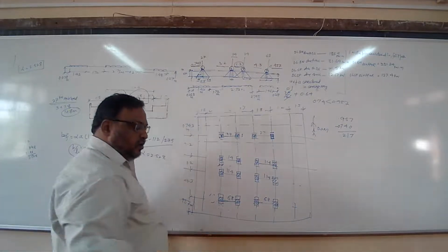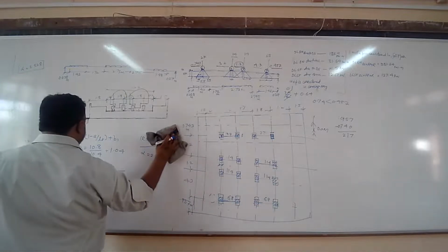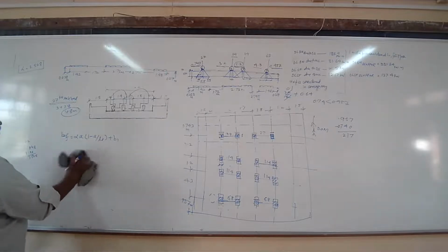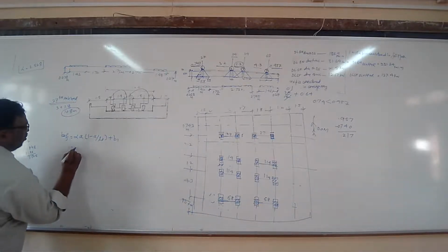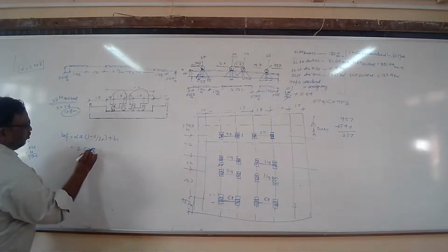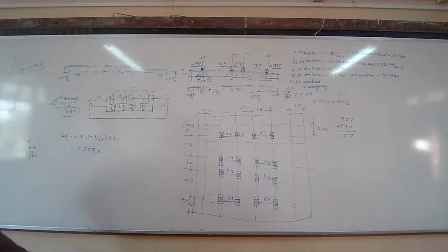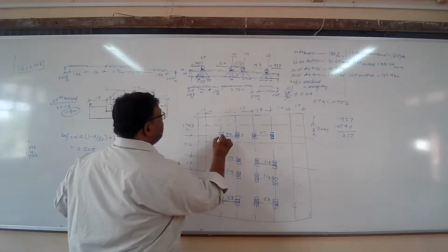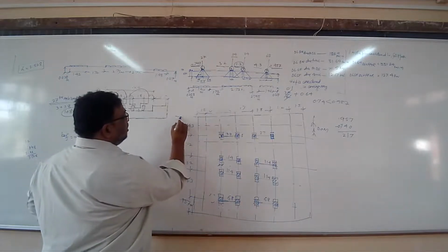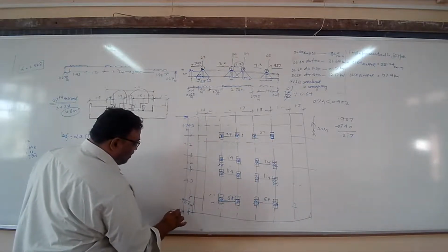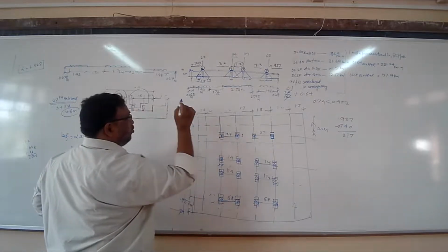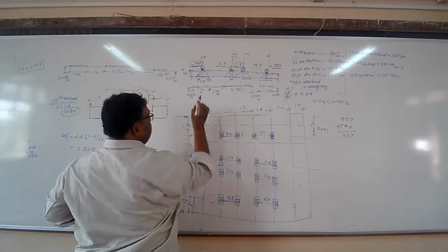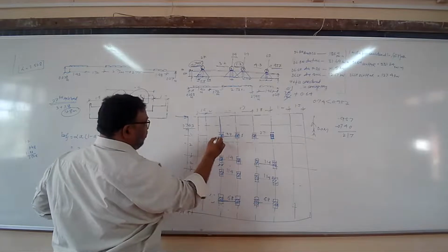Okay. Now after getting alpha, get these bits up to which the effect of this load is 2.528 into A. What is A? A is the position of that concentrated load under consideration from the nearer support. So this is one support. Here is the another support. So this is the nearer support. So how much that distance is? 0.743 from the nearer support.